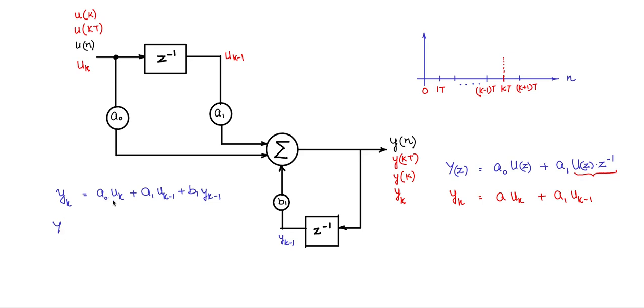Now if you see here, the polynomials, if this is a polynomial in z, the coefficients of the terms in the z transformed equation, and that in the time domain equation at kth with respect to the kth interval of time, the coefficients are all the same. So it is easy for me to move in and out of the time domain and the z domain.